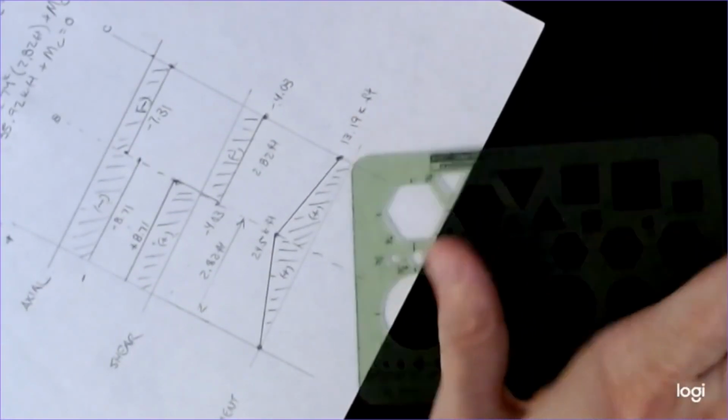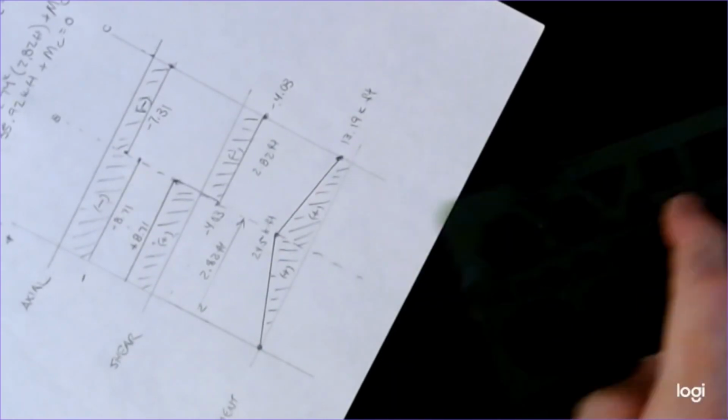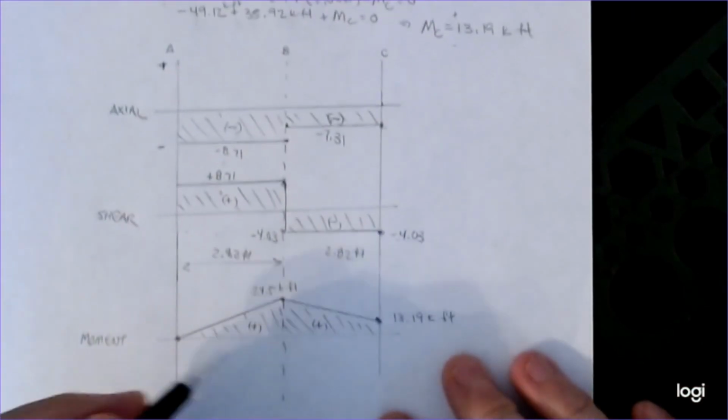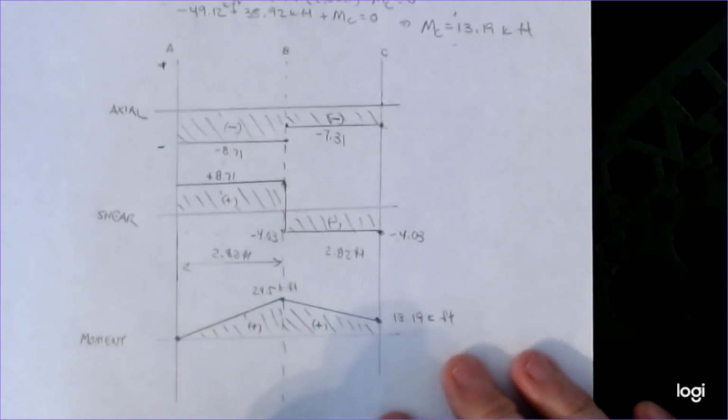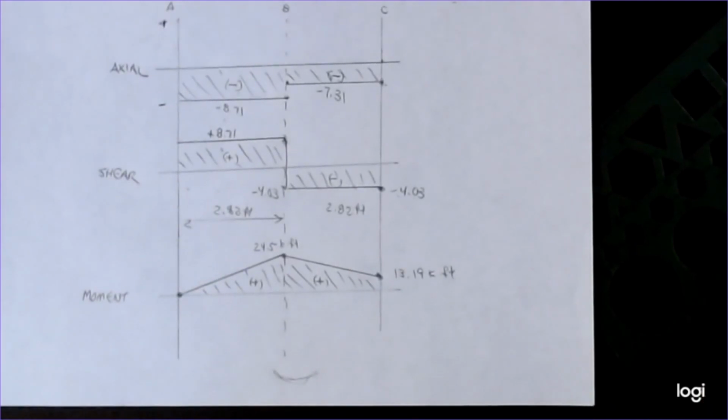Now, we drew it horizontally, but in reality it's actually oriented like this up the member. And then if we come back and do the beam, which is just like all the others that you've done, it would lay in horizontally along the edge. And that would be the moment diagram. We can go from the moment diagram to guessing which way it deflects. Remember, a positive moment causes kind of a downward deflection. So this is deflecting down in that direction. From that, you can start to get a sense of the deflected shape of this thing, and it deforms as you might expect.